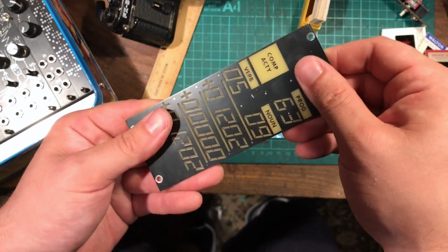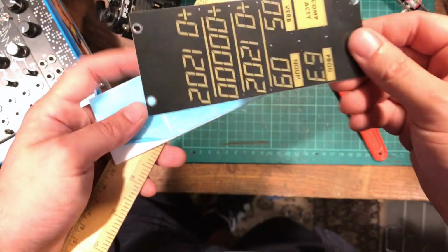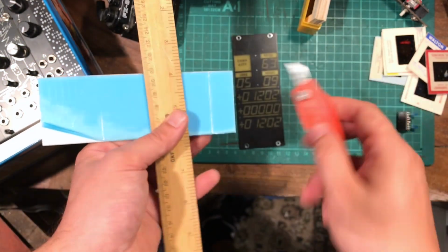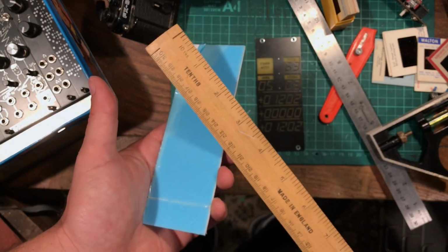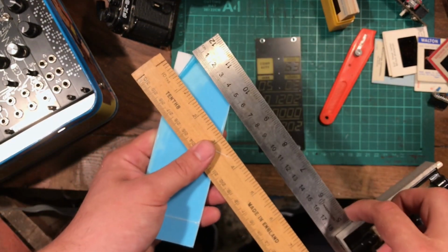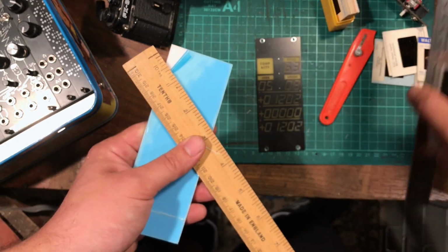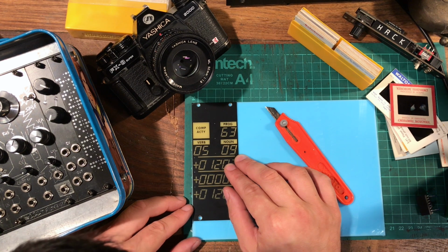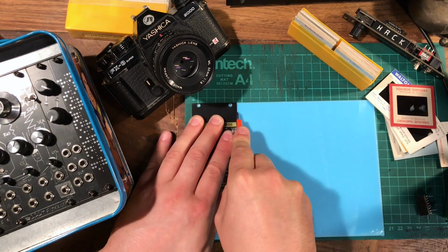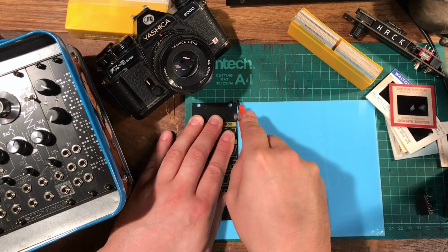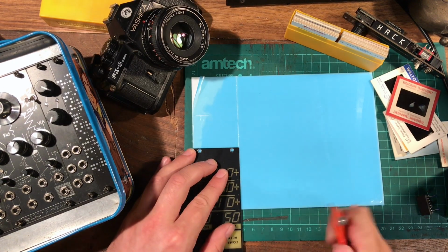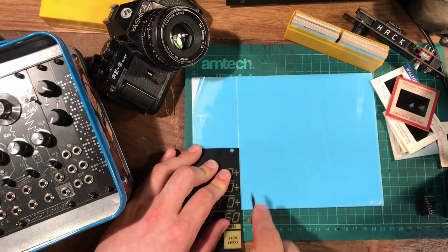If you're doing this with one of your own Eurorack panels that you don't want to get scratched, then you might want to just use it to measure and then use a ruler to actually guide the knife. And best to use a wooden or plastic ruler, because metal ones will likely start scratching all the surface of the acrylic. So I'm going to position the Disky panel so it's a little bit in from the edge, so we're cutting the panel a little bit wider, and you'll see why in a bit. And you just want to repeatedly score down and make a deep line in the acrylic. Now I'm just going to move the panel down to score down the last bit of this board.